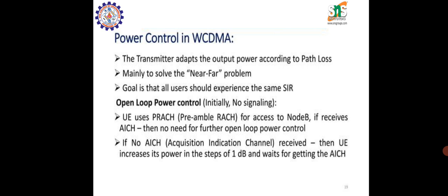Now let us look at power control in WCDMA. The transmitter adapts the output power according to the path loss, mainly to solve the near-far problem. The goal is that all users should experience the same SIR.